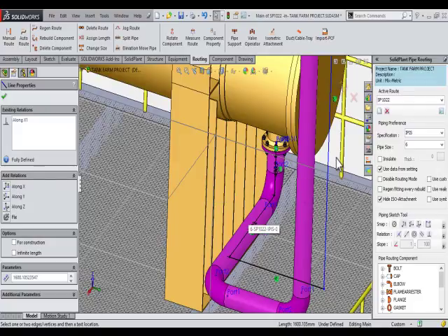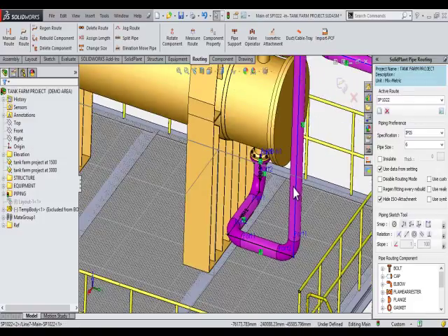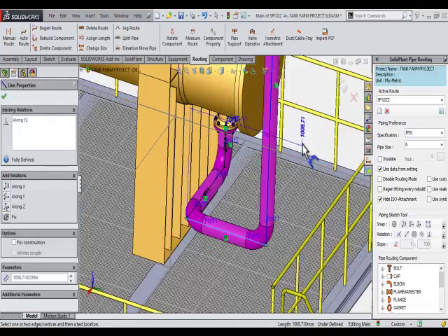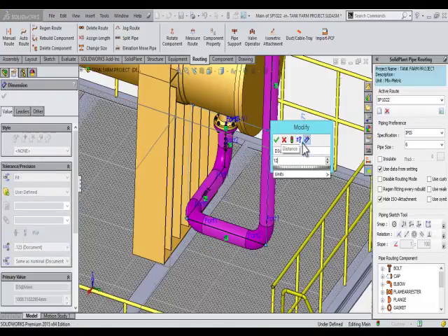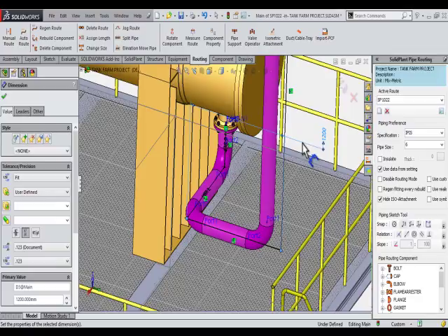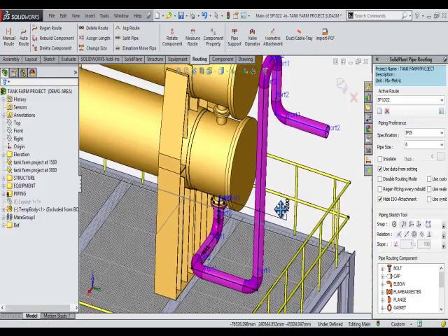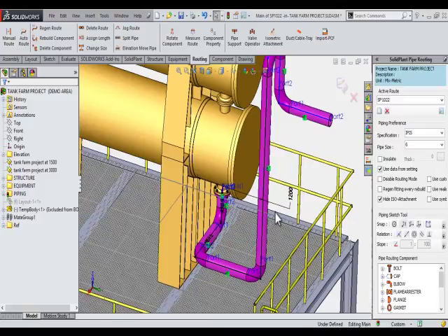Should you need to use a lot of the same segment of pipes in a route or in your plant design, we can also manually place a dimension on a sketch line segment. This dimension could reference the sketch, it can reference structure or other pipelines. It is a standard in SolidWorks three-dimensional sketch.